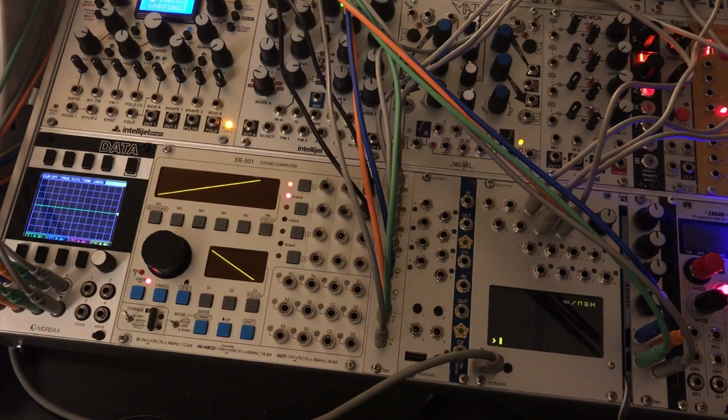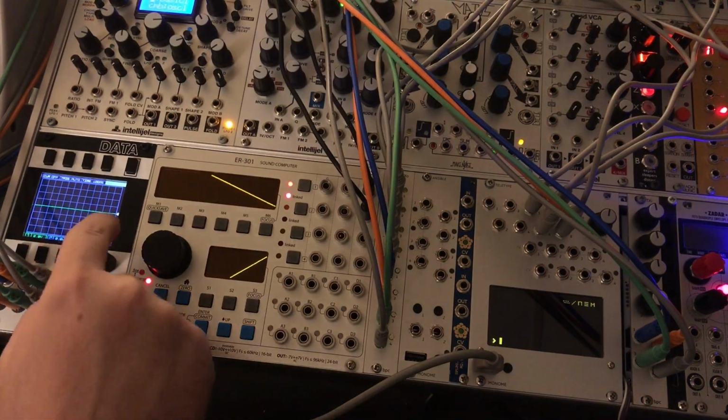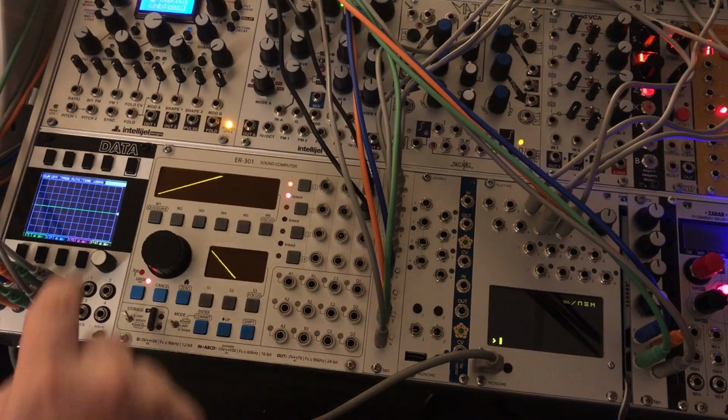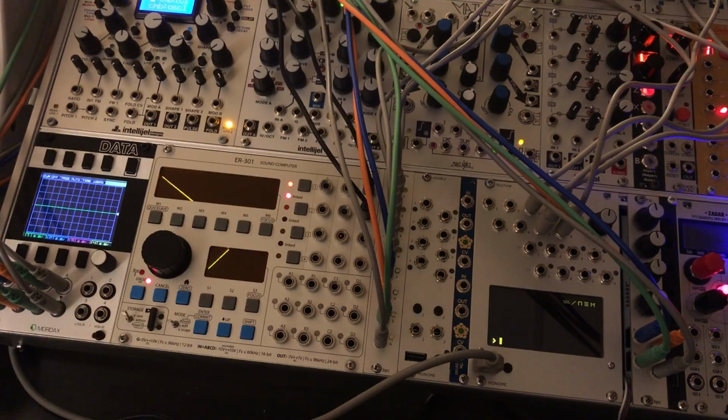But the important thing to note here is that, for any of these operations, the maximum voltage that it's going to put out is going to be defined by the CV value. So when you do this, if nothing happens, your CV value is probably still set to 0. So it actually is oscillating, but it's oscillating over a maximum range of 0 to 0 volts.